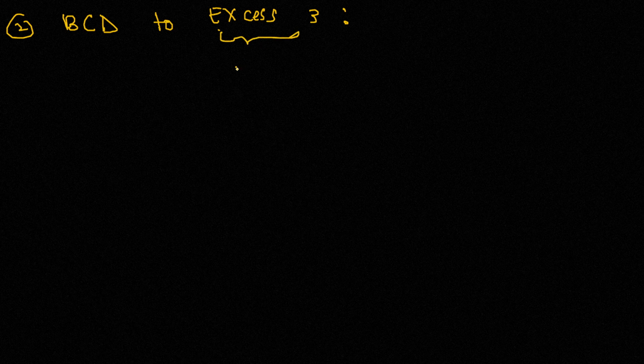So now let's look at the second one that we wanted, which is binary coded decimal to XS3. Okay, so XS3 code is a much simpler one to write when compared to gray code. The only difference is XS3 code always starts from 0011. So whatever is the binary number in BCD, all you need to do is add 3 and it will give you the XS3 code.